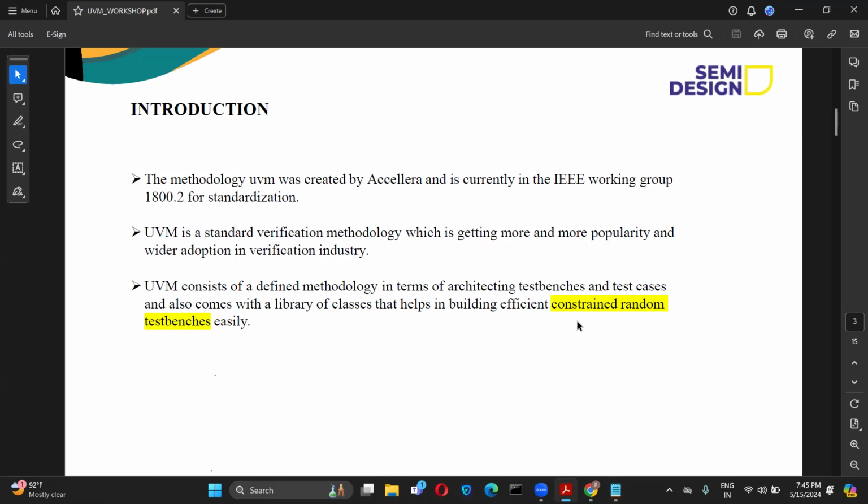As a first step, when we randomize, we will increase the count. For example, we will run the same test case for 50 or 60 counts. Then some possibilities will be covered, but some cases will still be left out. Those we have to cover through corner, that is, directed test cases, where you give the constraint. You can write one more test case where you check that only these things are covered and this is not covered, then you write a directed test case.